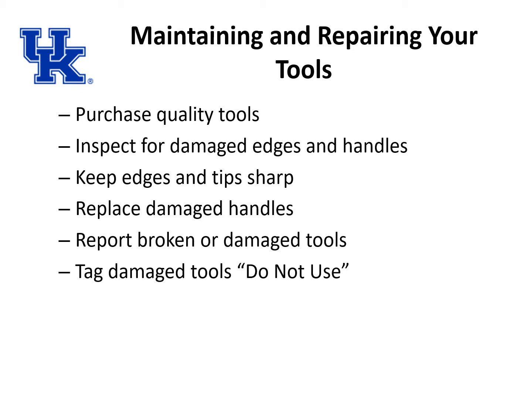Avoid repair and maintenance costs by purchasing the best quality tools. Your tools will last longer and are less likely to be damaged from proper daily use. Inspect tools for dull or damaged edges and damaged handles and grips. Wooden handles must be kept free of splinters or cracks and be held tight in the tool.